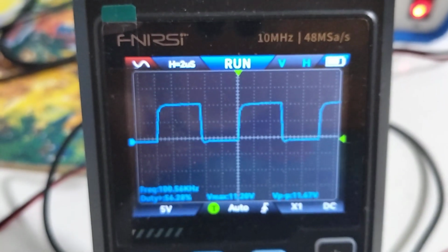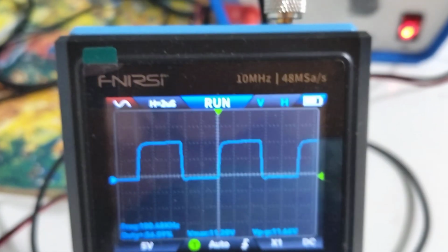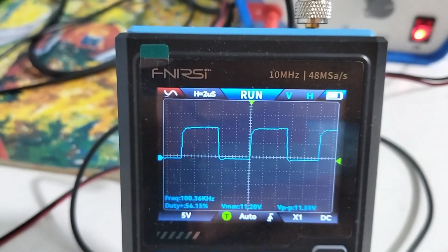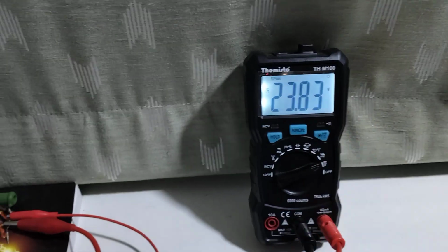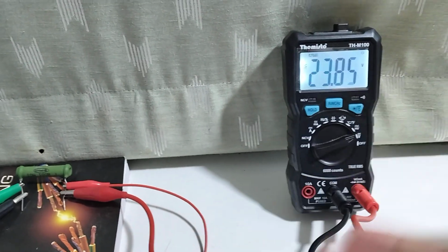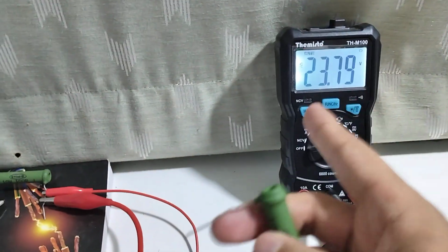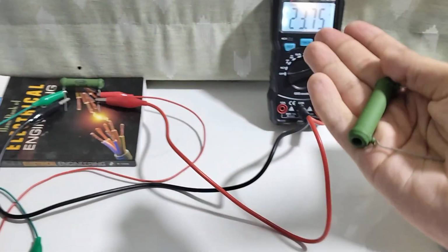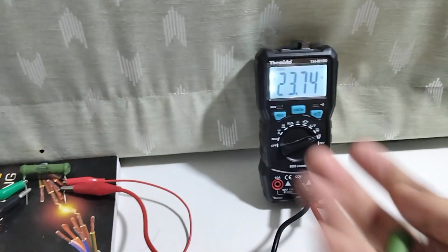Once you do a lot of closed loop control with PI controllers, you'll see how you deal with oscillations, steady state error and all of that. You can see here this is relatively stable, there isn't any oscillation. And on our output voltage, you can see here we have 23.8 volts. There's a tiny bit of steady state error, but as you can see live, it generally corrects over time. We're within about 200 millivolt, which should be close enough. And that's demonstrating our 24 volt, how through the ADC we're measuring and the PI controller is working.